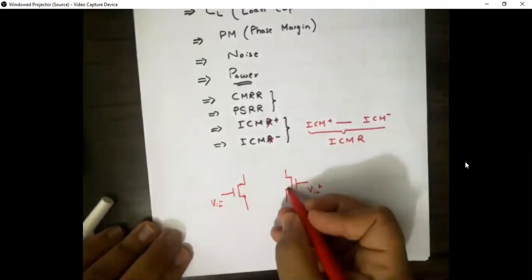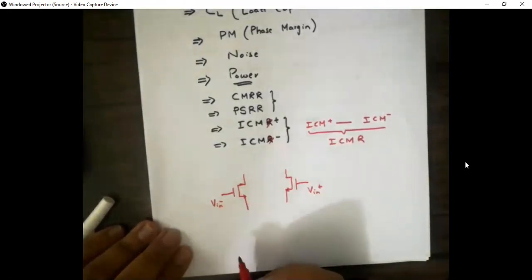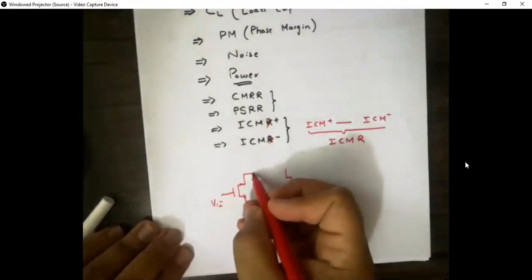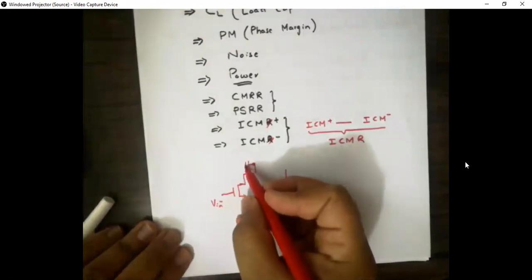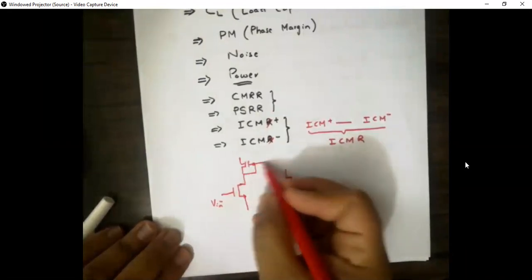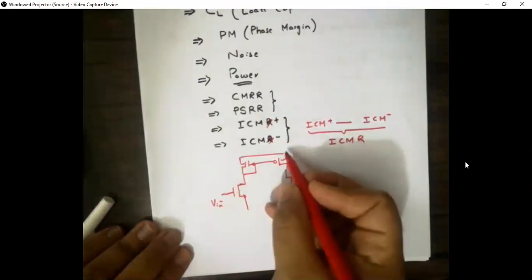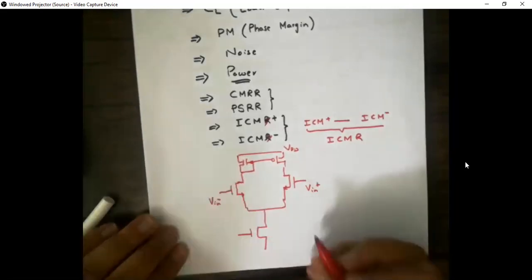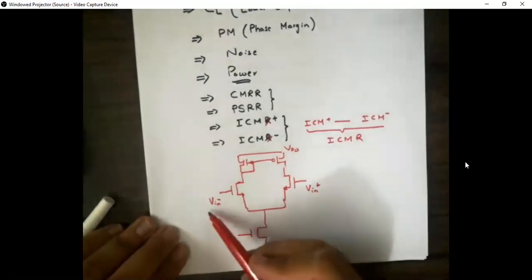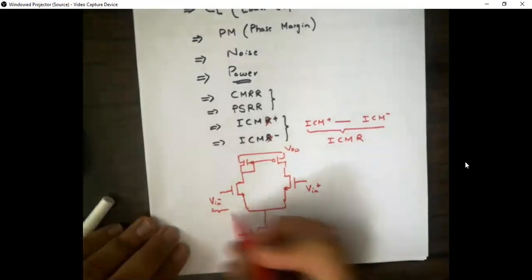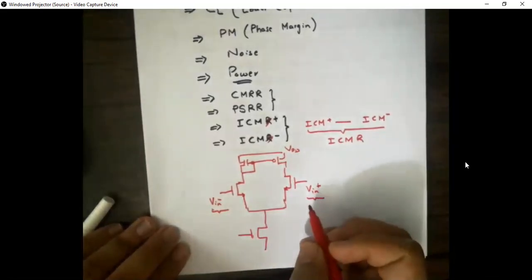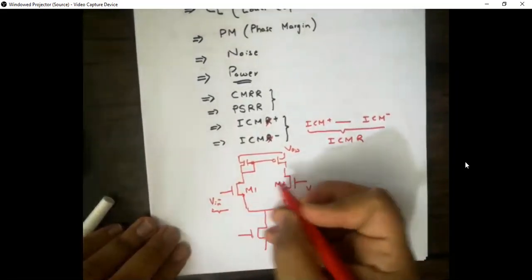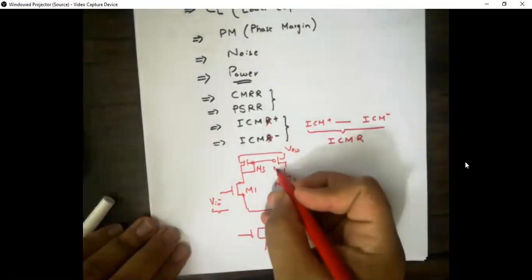So that range of input will ensure that, with a load connected after it, and VDD, that input range and the DC value of the input I apply here ensure that the transistors M5, M1, M2, M3 and M4 all remain in saturation.